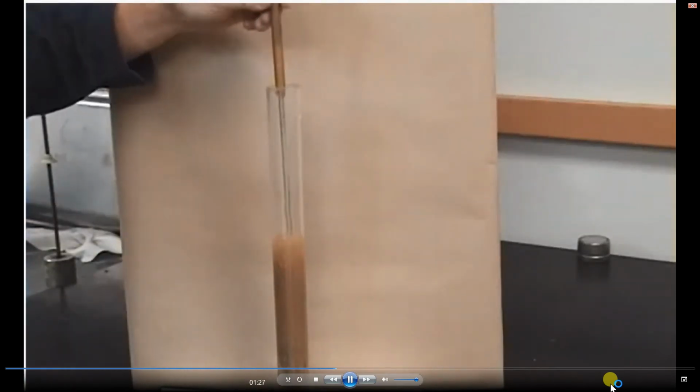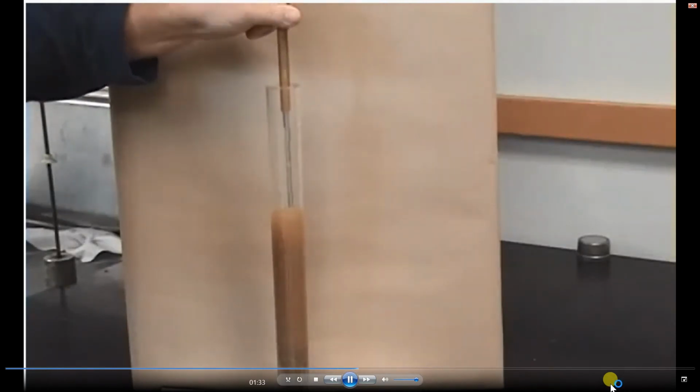When flushing the sample, push the irrigation tube down to the bottom of the sample in a twisting, turning motion while filling. This flushing and twisting will wash the fines from the bottom of the sample and bring them into suspension. Continue this procedure until you are close to the 15-inch mark. When nearing the 15-inch mark, be prepared to pull out the irrigation tube at the same time the cylinder fills to the 15-inch mark.